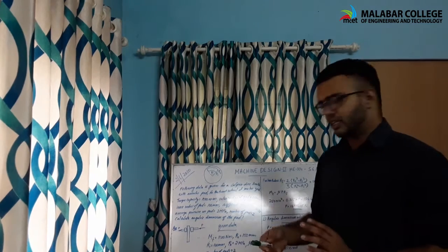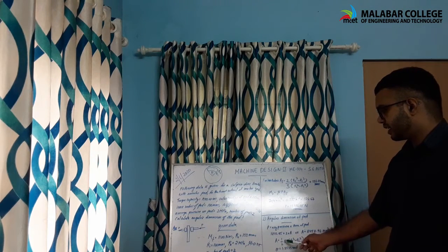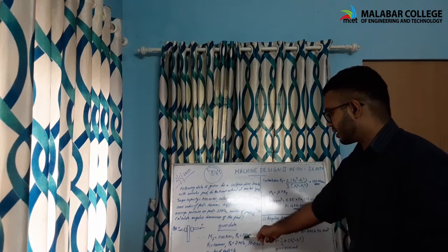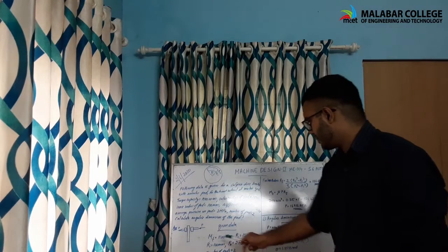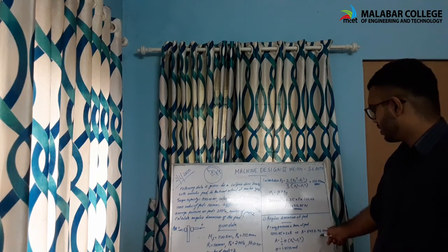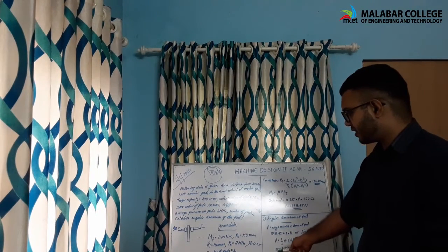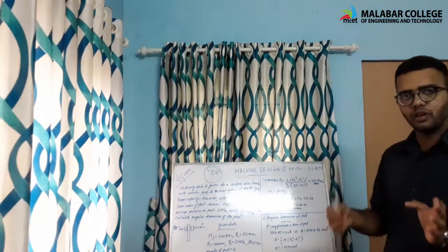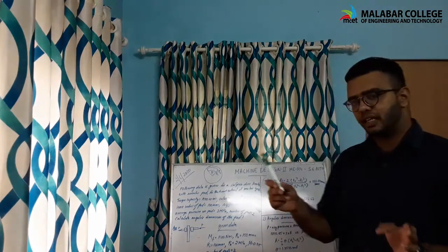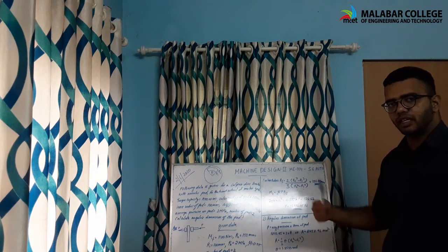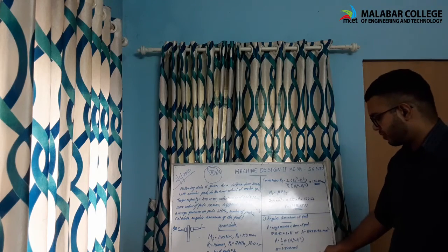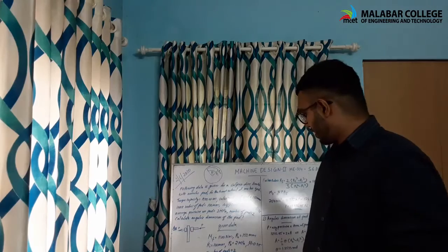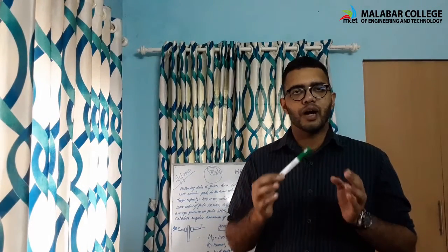Then we have another equation in the data book: A is equal to half into theta into Ro square minus Ri square, where we substitute Ro as 150 mm and Ri as 100 mm. With the area 8458.42 mm square, we can find the value of theta, the angular dimension of the pad. The value we get is in radians, so we need to convert it to degrees by multiplying by 180 by pi. The angle we get is around 77.54, and by rounding we get around 80 degrees, which is the angular dimension of the pad used in this disc brake.